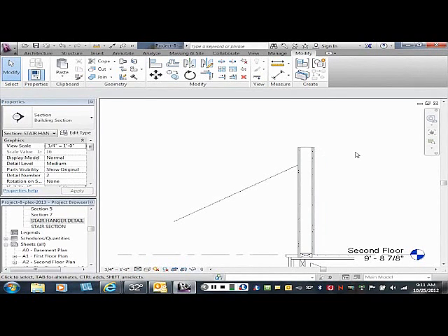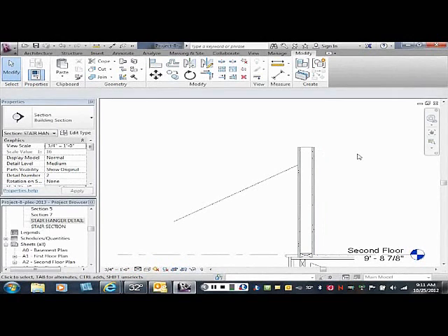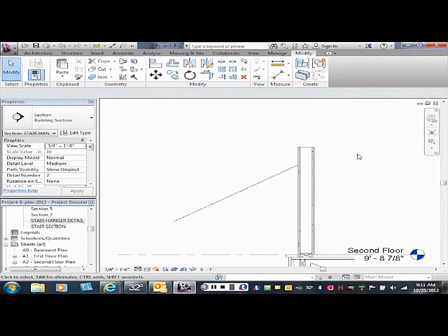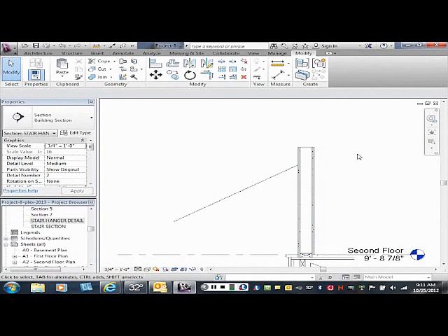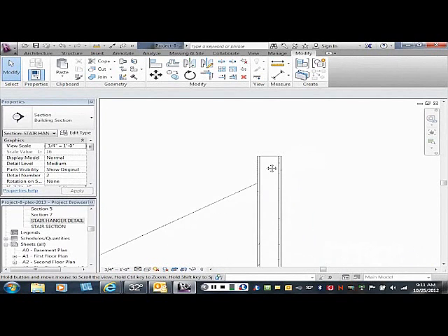We could put a wood cap on top of it. We could put a sheetrock on top of it. Wouldn't be real durable, but I've seen projects where they've just put corner beads and sheetrock at the top of that wall. Not very finished, but it does finish it. In this case, I'm going to put some kind of 1x board up there. Maybe it's a 1x hardwood trim board with some casings under it or something.